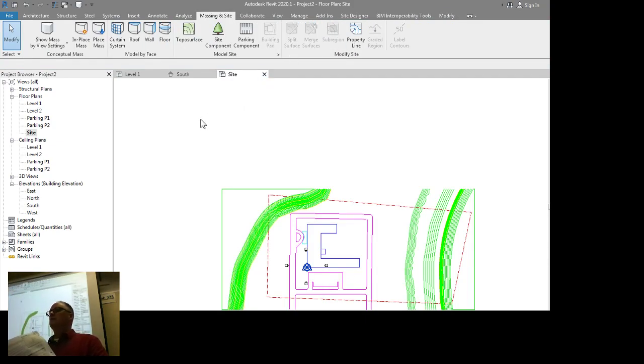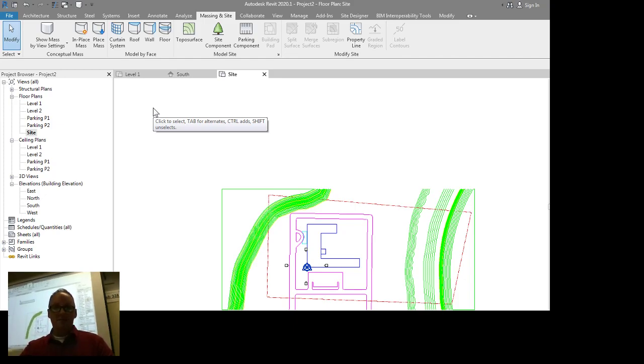Prior to using the Toposurface command, there's a little tool that's built into Revit that will help you identify what layers in your survey actually have topographic information on them. And it's mentioned elsewhere in the notes. I might not be in exactly the right place for that, but I'm just mentioning it now. So it'll be on YouTube for you folks.